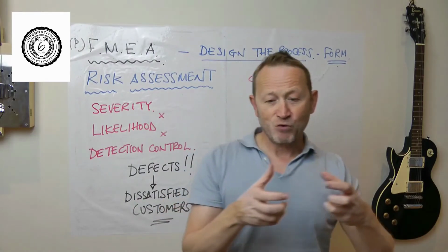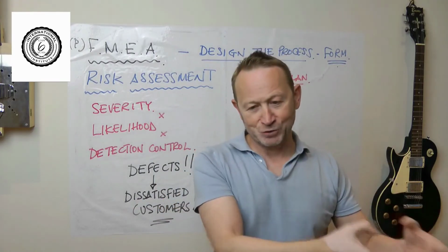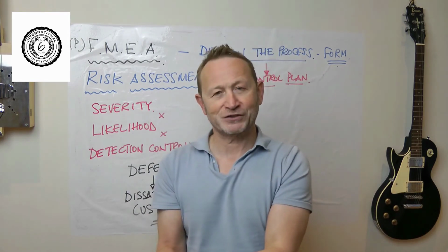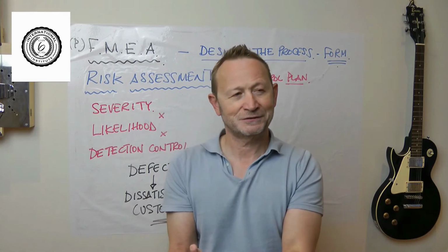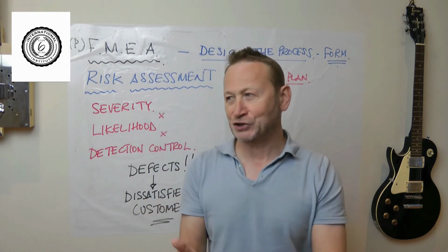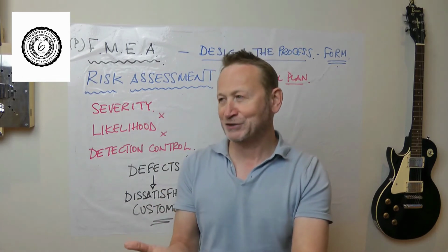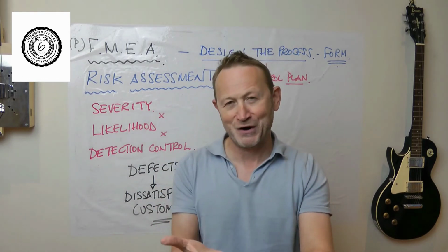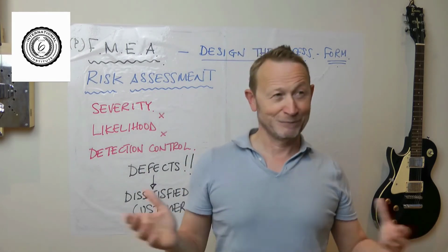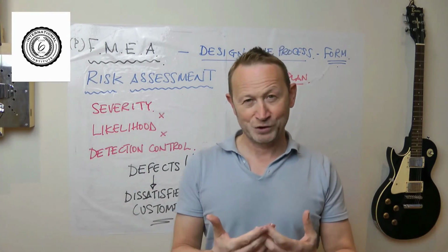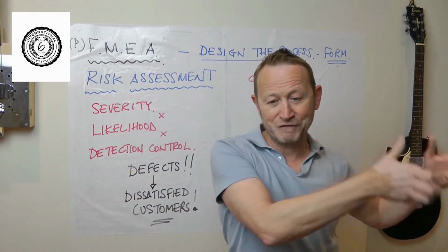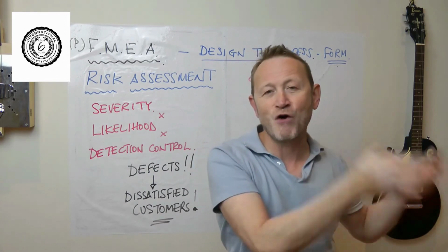Now, if I put that in the wrong box, if I say the failure mode is that I'm going to get white marks in the molding, then I say, what's the failure effect? Now you're having to think forward. You're having to say, well, there's going to be a high scrap rate. Maybe we're going to be late with the customer because we haven't got enough parts. Maybe we're going to delay an order to a big customer. Maybe we're going to lose a big order.